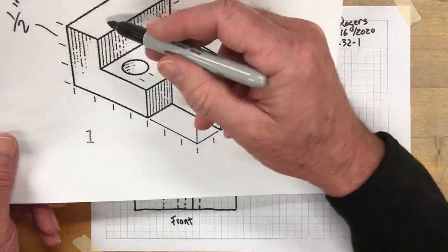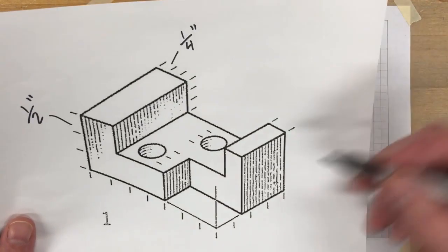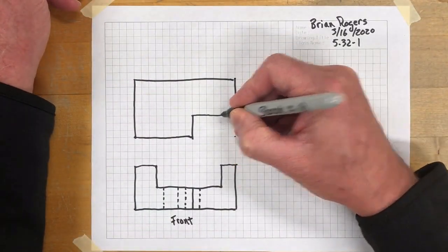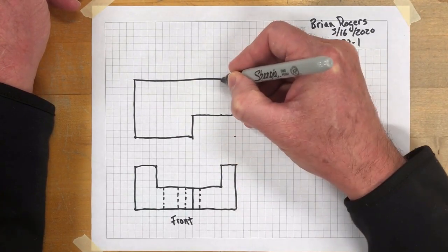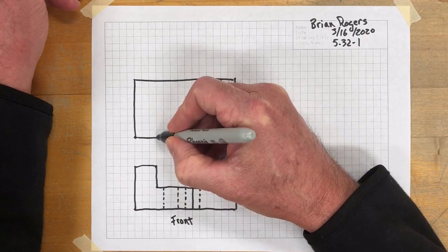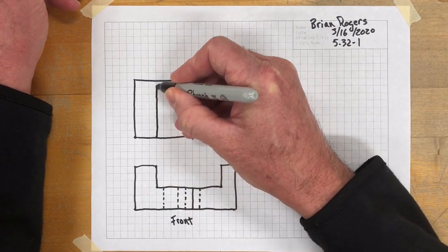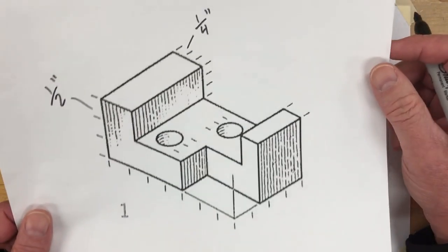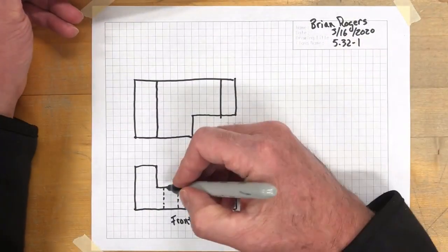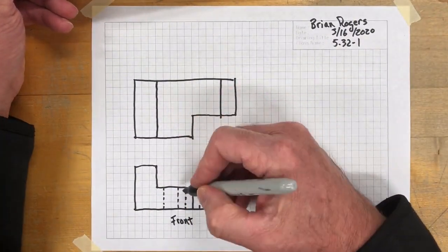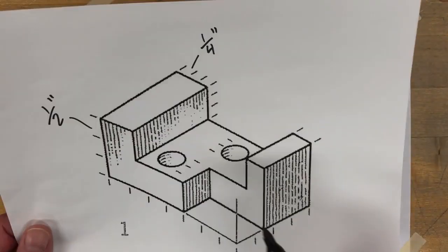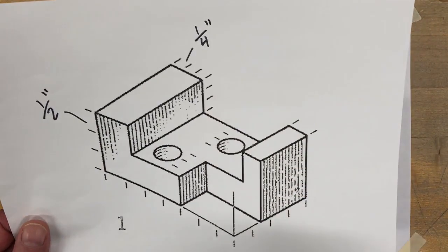Now I've got a couple flat spots I need to indicate in the top view. Okay, this flat spot and that flat spot. And so all I have to do is just project these up along this grid line here and draw a vertical edge across there. Same way on here, just project up, put a dot, vertical edge across. All right, so now the only thing I have left to do is take care of these holes. Now remember, we know where the hole is located from right to left because we can see its location in the front view. Now what I need to know is its distance from front to back, right?